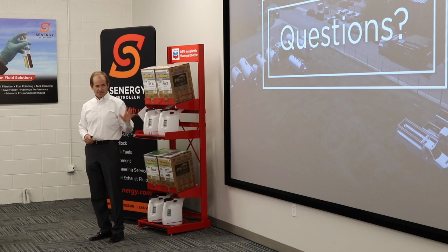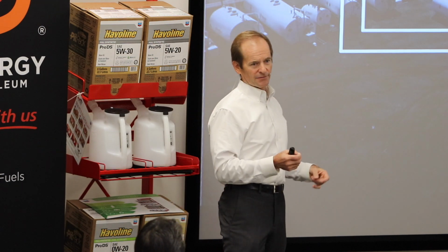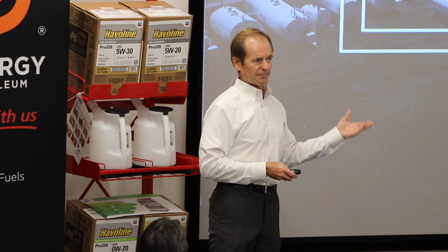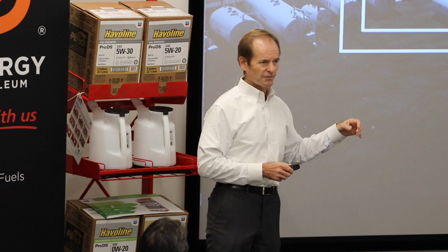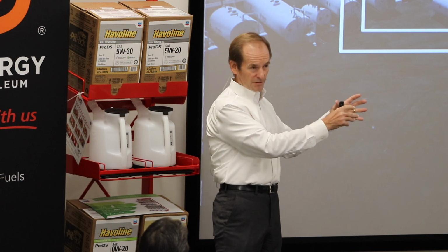I'll try not to spend too much time on it because one can digress. But when they do these test stands, they build very specific engines for these. And more importantly, it's specific parts. If you're trying to test bearing wear, I'll go for an example with bearing wear. You don't just go to SKF and get some bearings and put them in, or from whoever's making the bearings for that particular engine. The bearings are very specifically manufactured. They have to meet very specific standards. They're very carefully weighed and designed, and usually they're done on a specific run, so they're serial numbered.